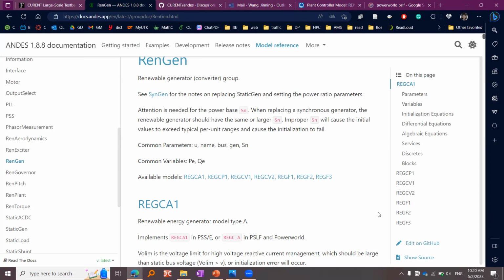Now, you can't have a situation where everything is inverter based, right? So you need at least one that's providing that. But with grid forming, people are now trying to put lots of them together so that they have the capability of providing a frequency signal. Although usually you have to have some sort of leader follower arrangement, so you're not fighting each other.